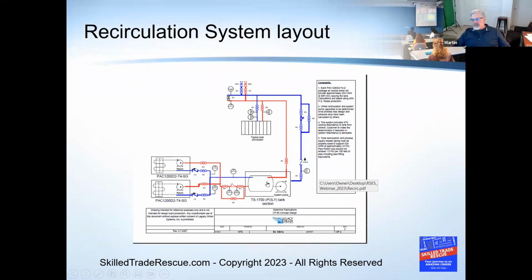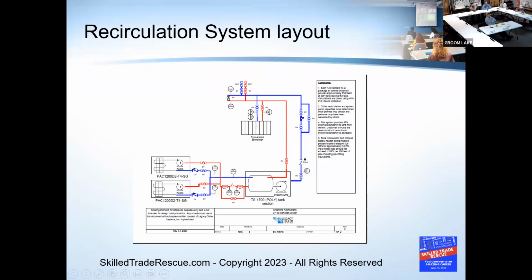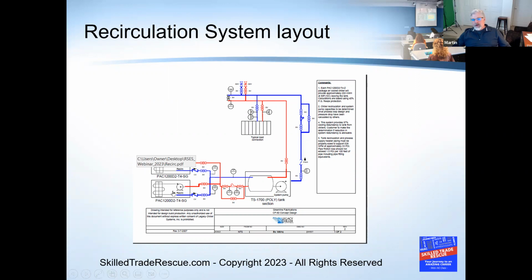That's the benefit of having a buffer tank. In a plastics plant, they'll baffle it to where it'll have holes in it, but more of the warm water stays at the chiller inlet, where the colder water is dumped into the area of your system. Yep. We never did that, because what we would do is upsize these recirc pumps so there's so much turn in here. We experimented with baffle tanks a little bit, and we found that we'd rather have just big pumps doing it. But yeah, that's another way to do it for sure.